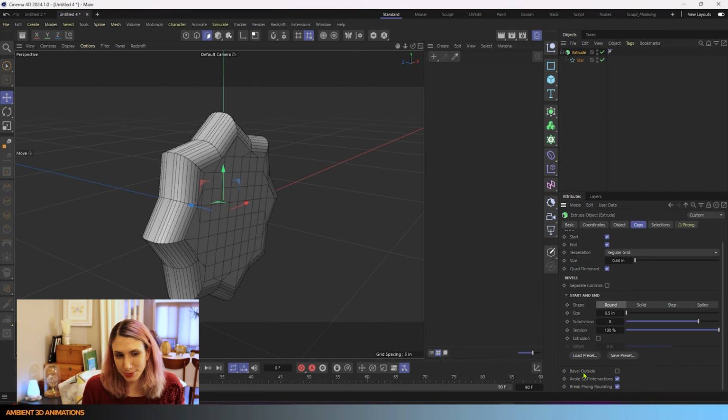And we have these other options out here. You can bevel the outside. This is usually turned off because when you bevel something, Cinema 4D automatically compensates by making that object smaller so that when you bevel it, it doesn't look like it's getting larger. Now, if you turn on bevel outside, it will allow the form to expand to compensate for that beveled form on the edges. If you leave that off, it will not become larger like what you see on my screen here.